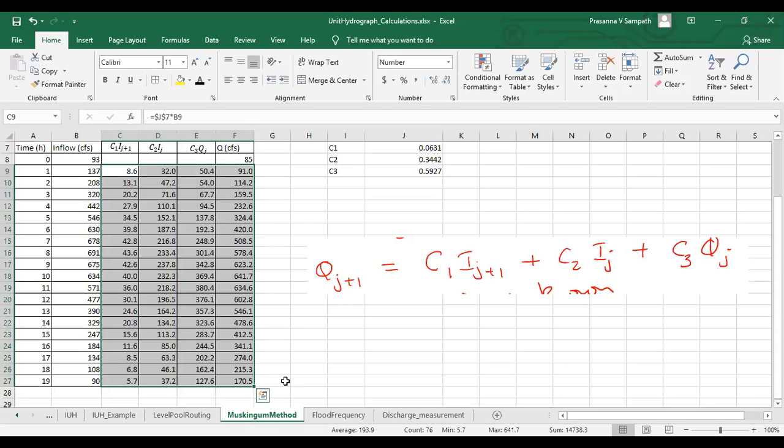Because the people who are making the decisions were able to predict what the flow rate will be at this point, they were able to compute the areas that will get flooded, which may cause some dangerous situation, so we should evacuate these people, move them to a safer location, and then they will be fine. That is the whole idea of this Muskingum method. It allows you to estimate the way the discharge, the way the flood, will propagate through a channel reach.